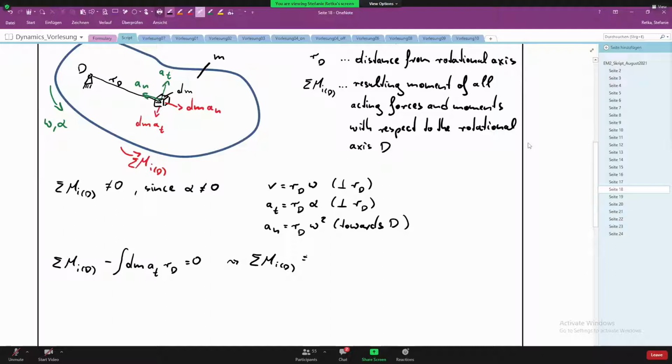This is an inertial force, and the inertial force acts against the change in motion, meaning that it always acts opposite to the acceleration. When I accelerate an object, then I change its current form of motion. It changes in speed and or it changes in direction, depending on the type of acceleration. So I changed the motion of the object. It's not a static system anymore since it's being accelerated, and the inertial force acts against this change of motion. And that's why it always points opposite to the acceleration. Okay, thank you, Professor. You're welcome.